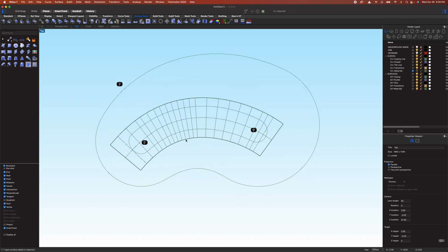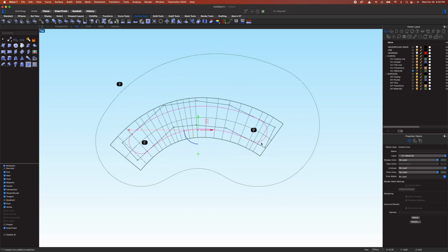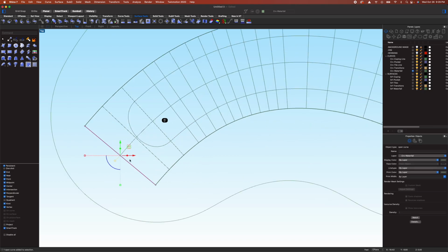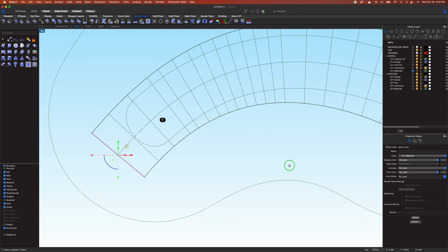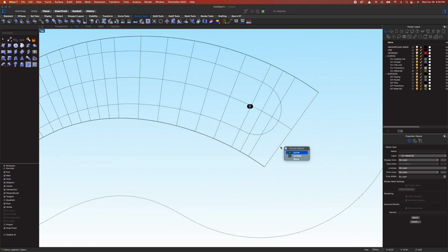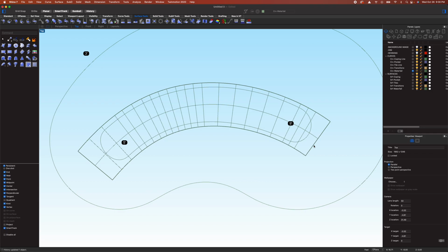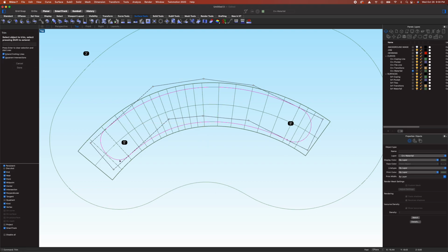I kind of want to tighten this surface up. I'm going to trim it right here, but I want to tighten this surface up first. So since we have history turned on, I can actually change the scale of these. I'll make it just a little bit tighter. We'll select the curve over here. Again, scale one direction. And maybe right there. Looks nice. I'll just leave those ends as is. Now we'll select that again and we'll trim it.